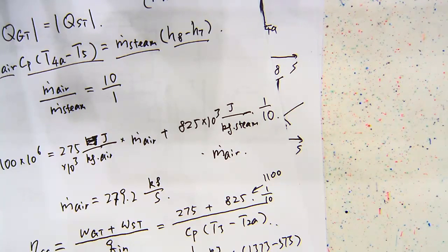Are you saying you want to directly apply from T3 to T5, or just T3 to T4? Is this correct? In this diagram, T2 over T1 equals T3 over T5. Yes, if you're using everything as a stagnation property, and if this whole process is ideal.